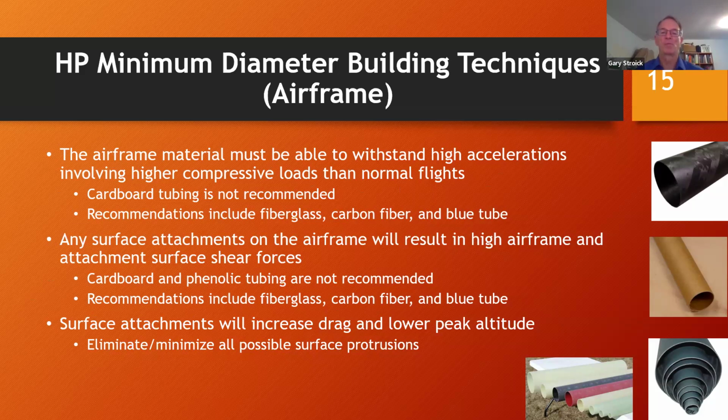Let's move on. I actually have one comment. Sure, go ahead. Canvas phenolic is, my perception is, a souped up phenolic tubing that's even tougher than blue tube. Are you familiar with that product? And if so, would that come in the not recommended or the recommended category? I think that would be fine, actually. You could certainly use that. We didn't put it on the slide, but I think canvas phenolic should be fine for what we're doing with this competition. Okay.